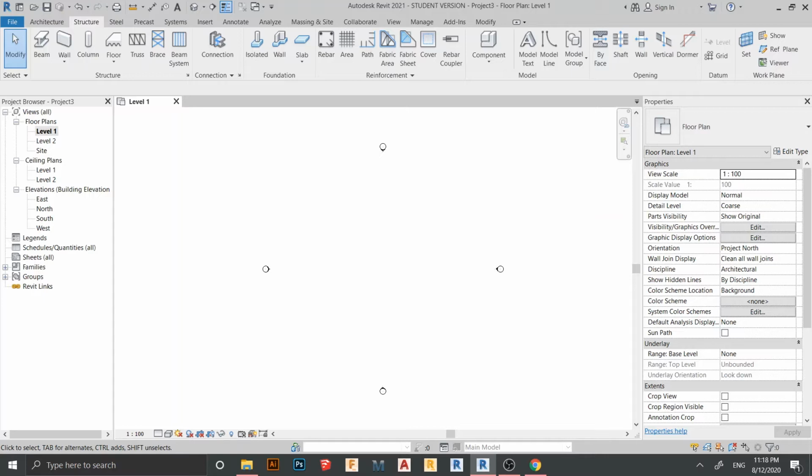Okay, this is a quick way to create a roof structure using beam system, and we will see that with beam system we can create multiple shapes and multiple projects. This is the way we can create our first beam system and roof. Sometimes you can use beam system for decoration, for wood panel or for ceiling. So I just give you a quick tutorial and example so that you can know more about